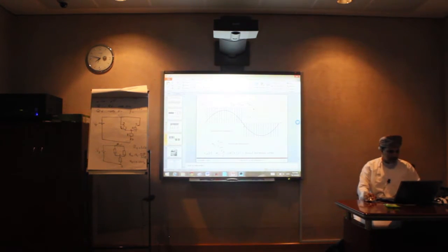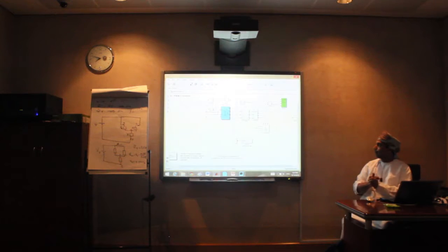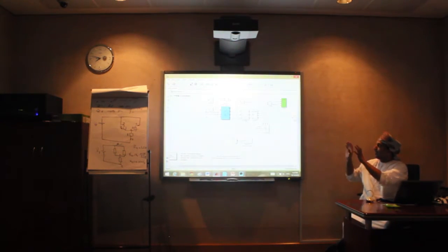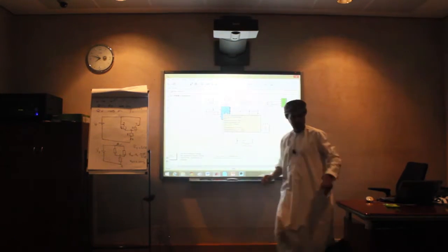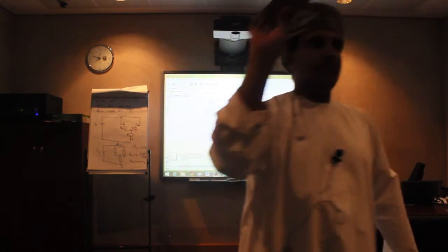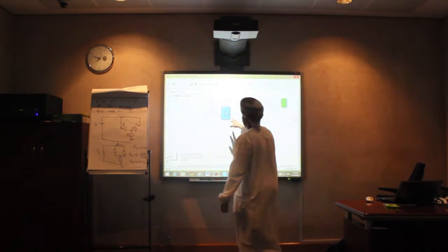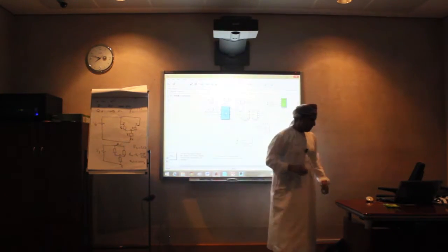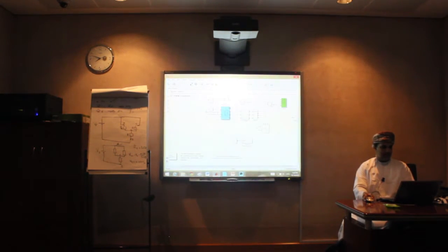So let me show you the operation of this one in this MATLAB simulation. This one will show you exactly how it works. You will see this is a battery here, and this here is an IGBT average, you can assume it like what you have now. It has 6 switches like that one. So you can assume 6 switches inside that one. And then those output pins, so this is the input pins, and this is VA, VB, VC, and this is the gating where we should send the signals.